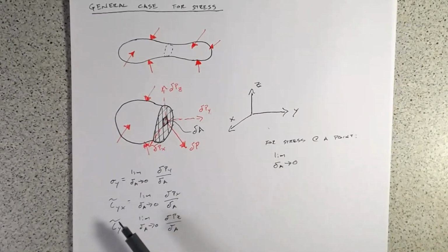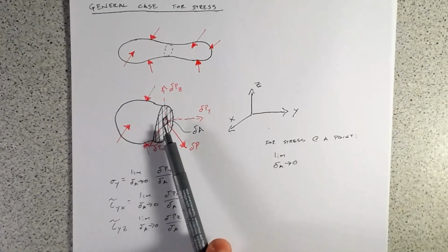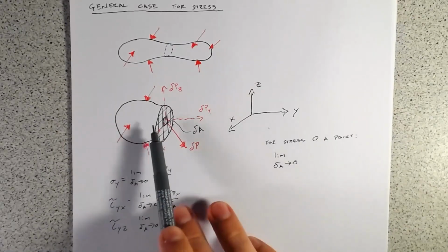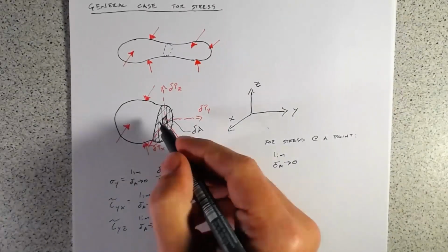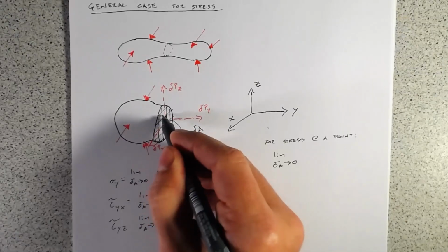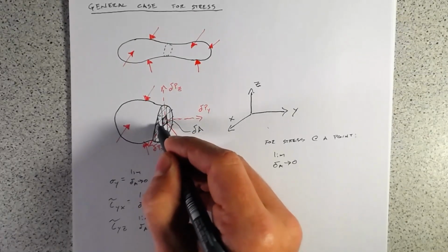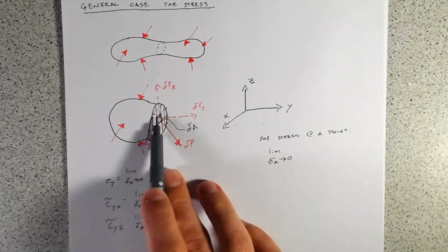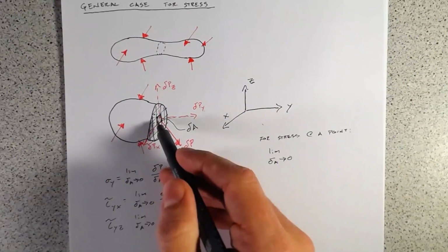If we want to know, well, what's our relationship of a stress state, and how does that relate to adjacent forces next to it? Well, we need to go from a section and really take out a tiny little cube from this box, and then look at what are all the stresses on each face. So let's do that.